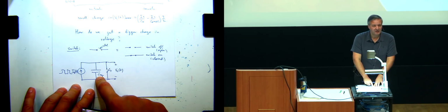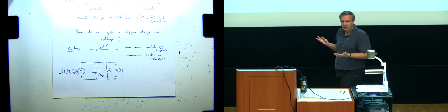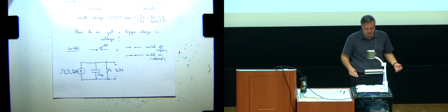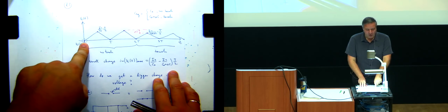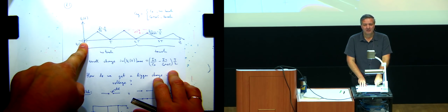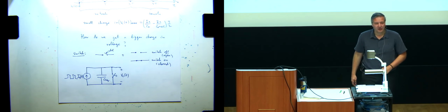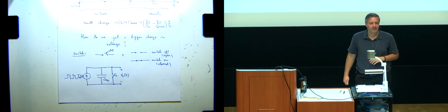Voltage across the capacitor is 0. Across the source is 0. Nothing really happens. When we open the switch, that's when the action starts happening. That's when the source starts charging C equivalent. So we can always know when this time happens. Right? That's just a convenience, basically, to be able to control when the measurements happen. Does that make sense? Okay.